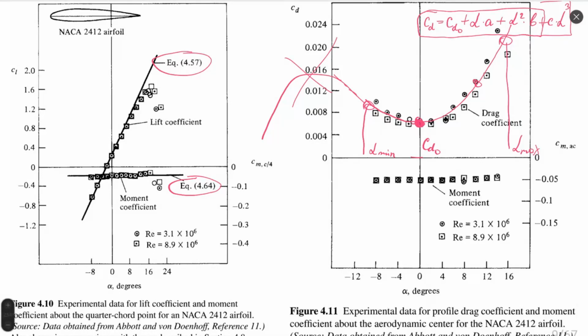So you must be very careful to apply this parabolic function, especially of more than second order, because having more than one extremum, you can find this extremum exactly in the middle of your region of work, and this will destroy completely the analysis of aerodynamic characteristics.